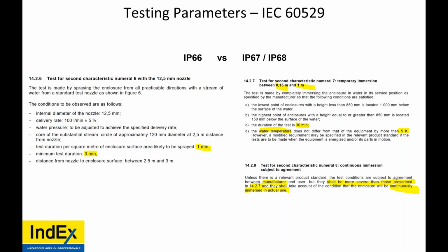Now, some equipment, let's say a gas detector, may have a deluge baffle which goes over it. When you change it, it says within the certificate and the data sheets that if you use this, it tells you the changed IP rating. But independent sunshades, rain hoods, those do not reduce the requirement of an IP rating.